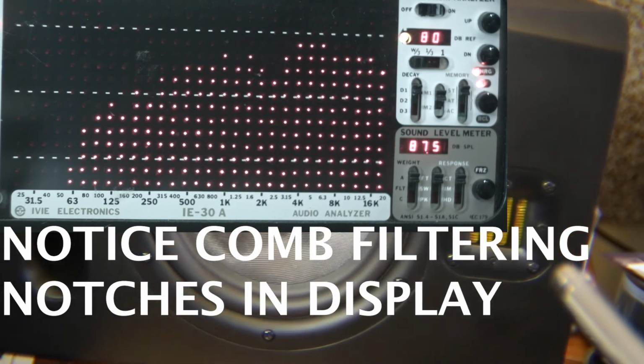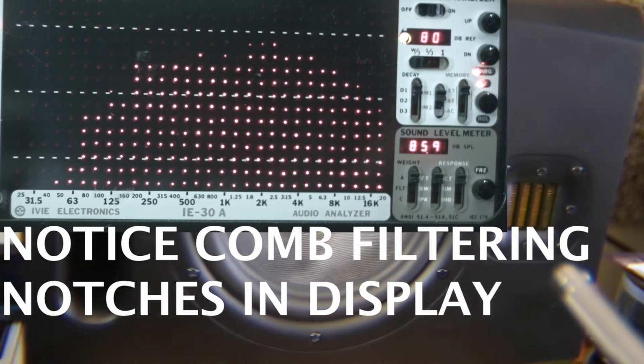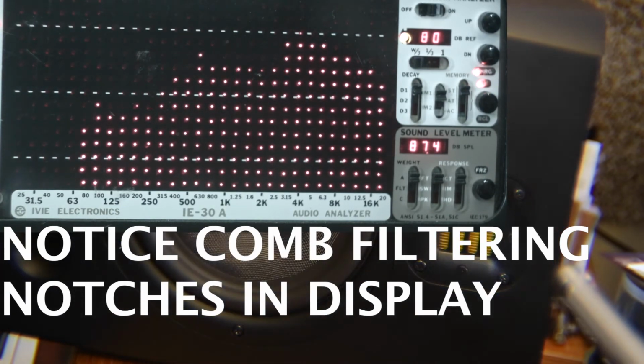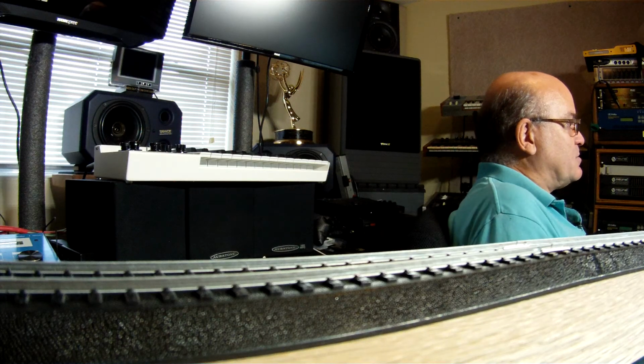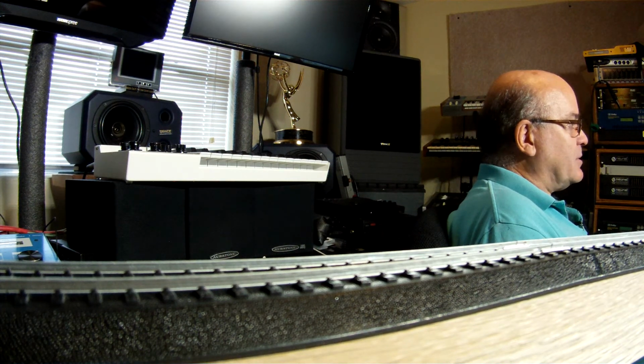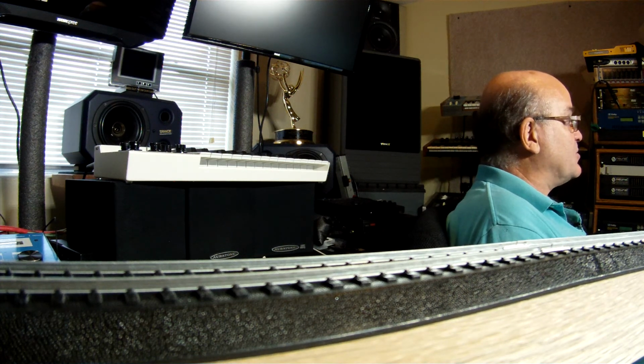If you walk between 2 speakers like in a mall or a theme park or something that have overlapping coverage, you'll often hear this little swishing sound as you walk in and out of the coverage patterns between the 2 speakers. It's most particularly noticeable in the upper frequency range. A lot of guitar players will describe it as sounding similar to a flanger effect.